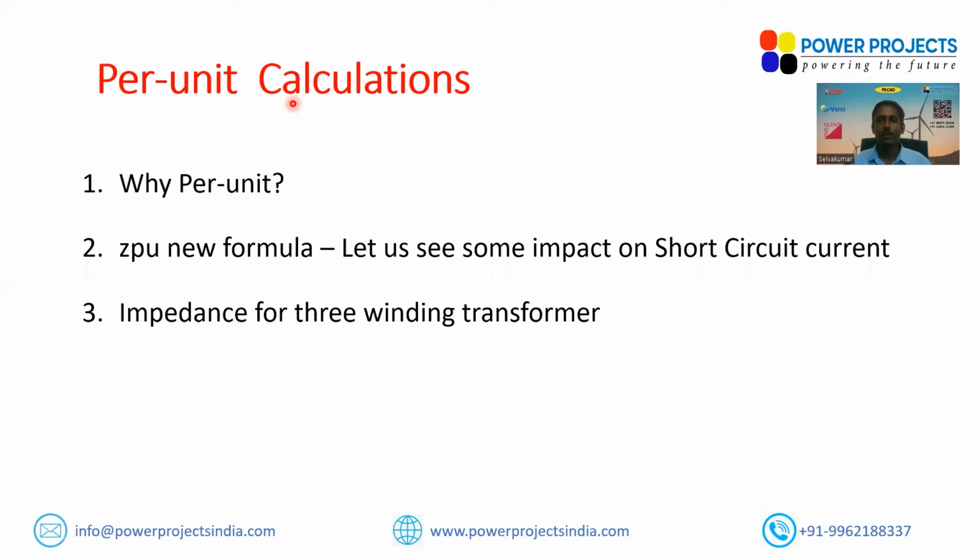air forced? The question is that you will not really test the transformer impedance at its rating; probably you will be testing it at some other values. The impedance value will not be the same. Means, 10% on 80 MVA and 10% on 100 MVA are not one and the same. And it is important to convert impedance from one MVA base to another MVA base, which you might need for multiple applications, because you will be having multiple equipments in power systems.